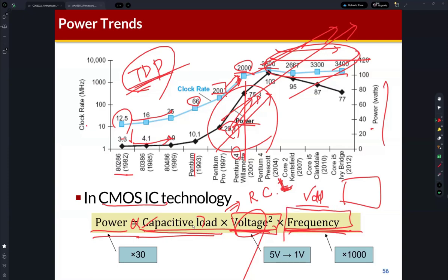And then clock frequency. Because the clock signal changes from 0 to 1 or 1 to 0 periodically, the voltage level changes periodically. When the voltage level is changed, power is consumed. So what does frequency mean? Frequency represents how many times the clock signal changes in a unit time. If the frequency is high, then a circuit will consume more power. So this is the power consumption equation.